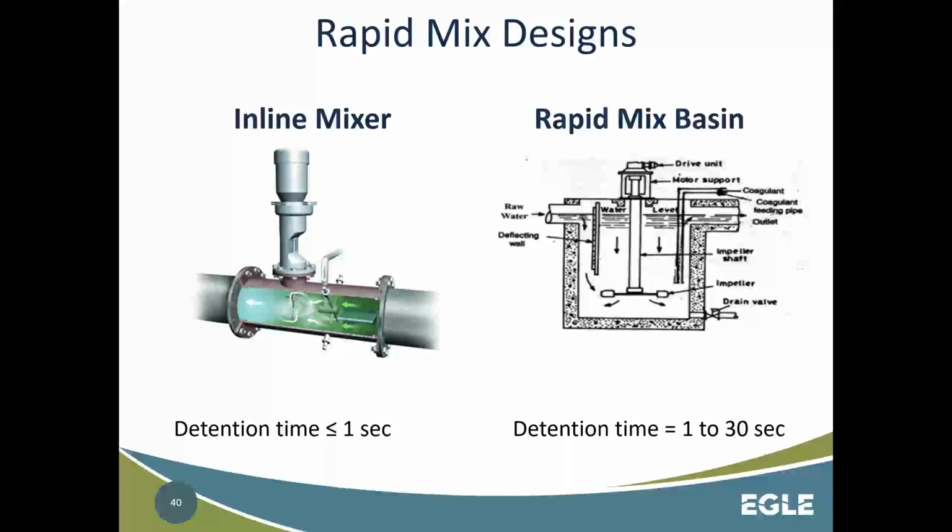I think in this case they're both adjustable in terms of being able to adjust the mixing velocity. So they're pretty much equal in that sense. I do think, again, this comes back to that photo where we had the inline static mixers, but you have to make sure they're in a place where it's easy to service the equipment for the inline mixers.